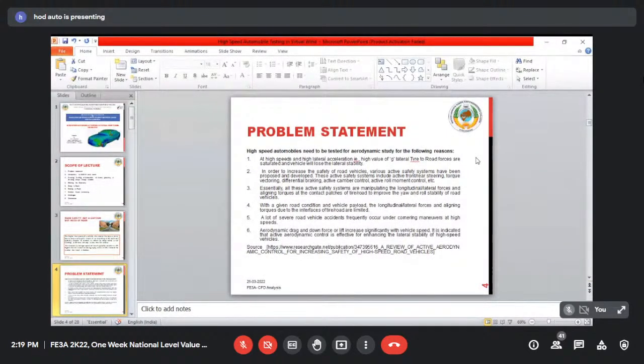I don't see more than that, or you can take a thumb rule of 30%, 33%. So 15 megajoules. Traction, mechanical losses, if you take them out, 15 comes to 5 megajoules, 1/3 again. So the active amount of energy that is used for traction is between 8 to 13%.